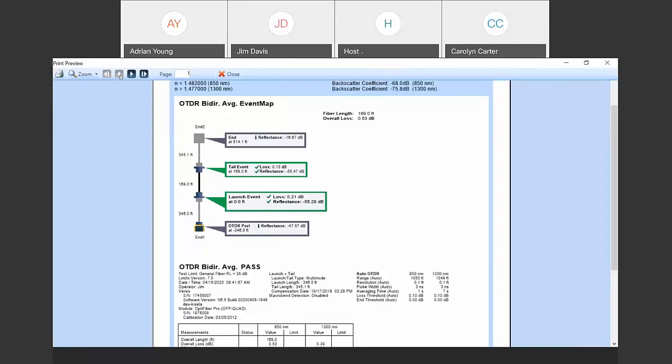The standard does specify the requirement for encircled flux compliance at this point. What we have recommended and what we have seen people do in the field is to use the mandrel for the loss testing with our test reference cord, which is about a 6-foot long. Good question. Okay. Another question that's come up is, so you did the testing at two ends.